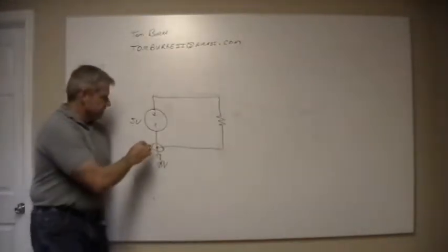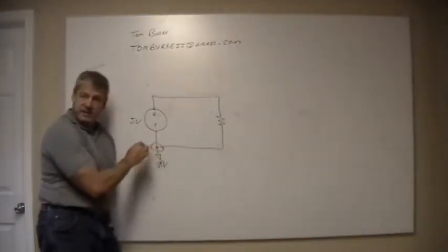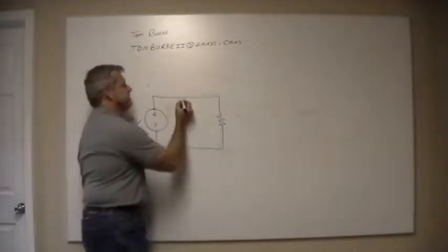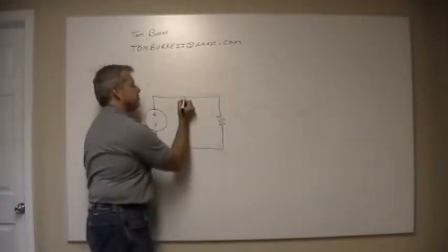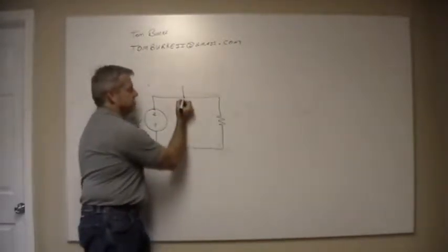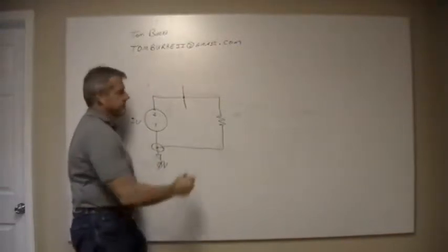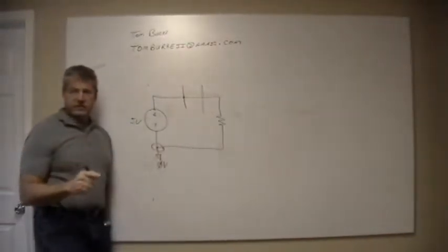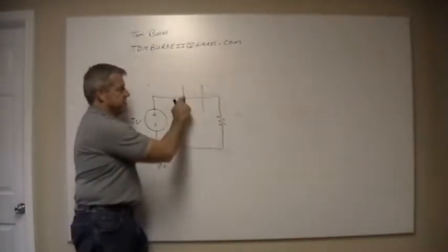Oh, we also talked about the schematic dot. The dot means that's where these 3 wires connect. Convention is you put a dot anywhere wires connect, and you don't do that where wires merely cross, because that means that wire crosses and doesn't actually connect, and sometimes that's hard to see.